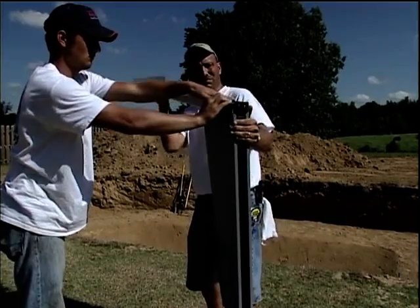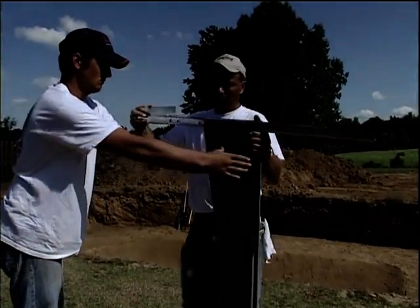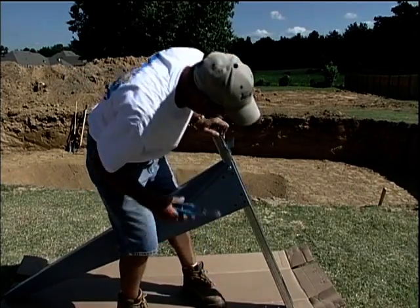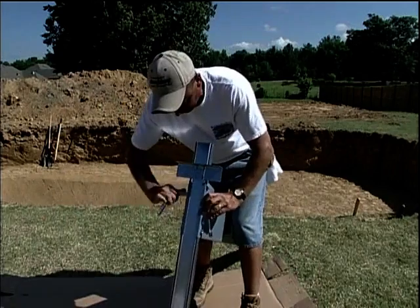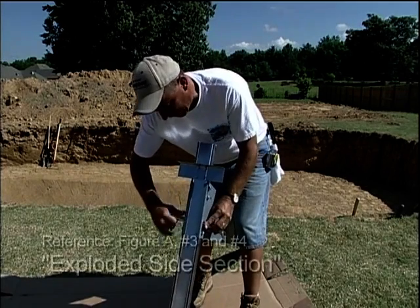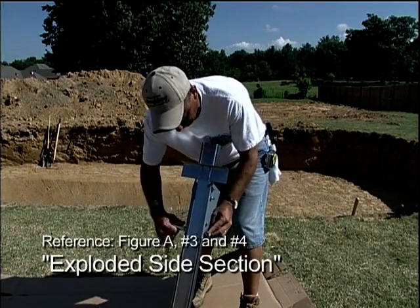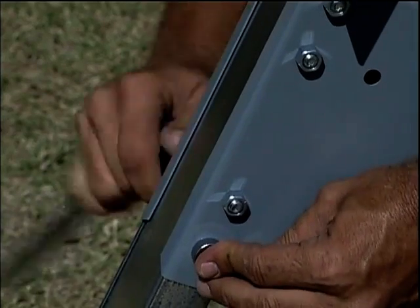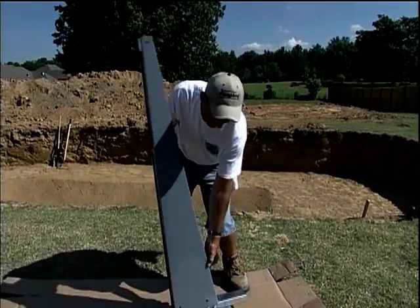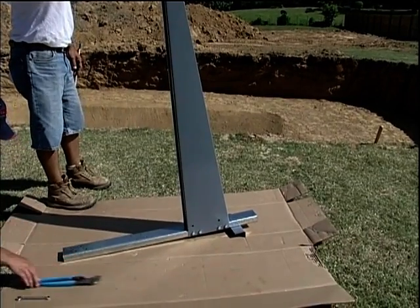Now slide the vertical into the end of the ground support sub-assembly until 4 holes align in the 3 parts. Fasten together with 4 3/8 16 by 3.5" long hex bolts and 3/8 16 hex nuts. Please refer to Figure A, Numbers 3 and 4, Exploded Side Section in your assembly guide. When making the assembly, it may be necessary to use pliers and a hammer to tap the bolts through. Be sure when doing this you do not damage the bolt threads.